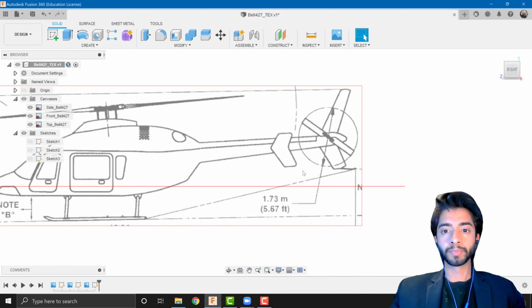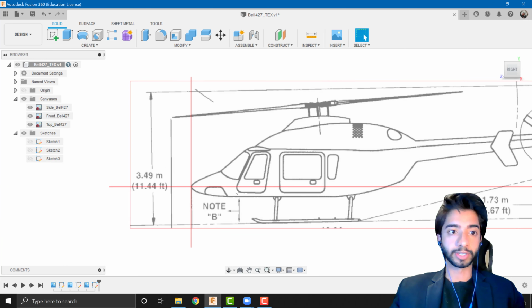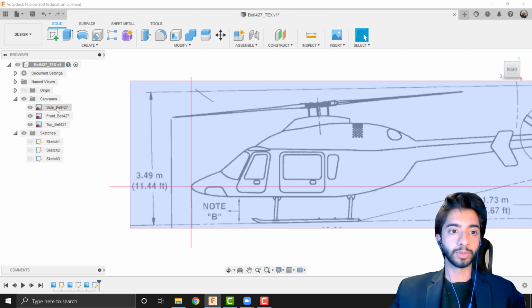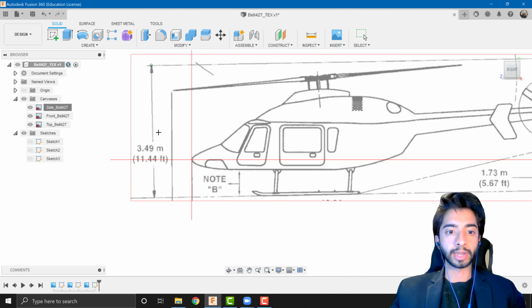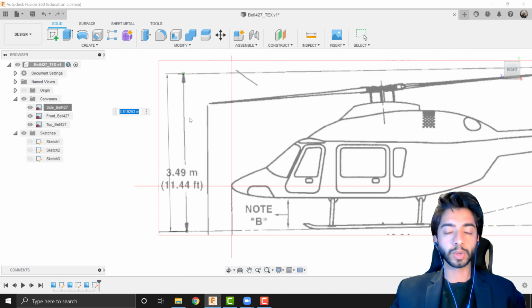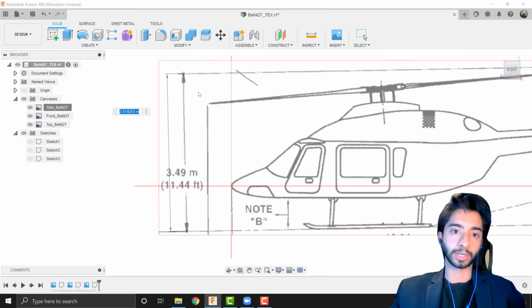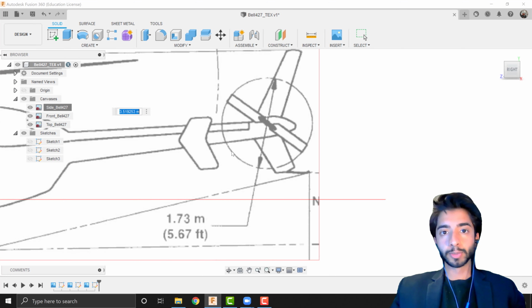So on the right view, let's go and recalibrate it. So right view is the side view. So I'm going to right click and click on calibrate. And I'm just going to make sure that I entered the right numbers by entering that. And it says 3.51. So it's in the same magnitude, which means we scaled it correctly, at least from this value. Okay. But this also means, let's have a look at the other